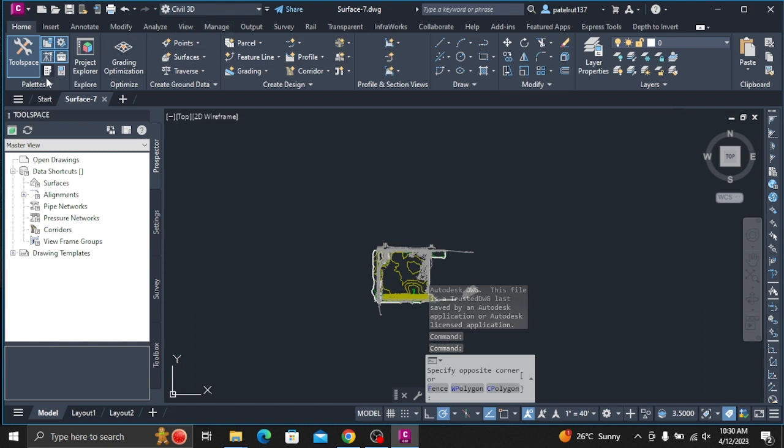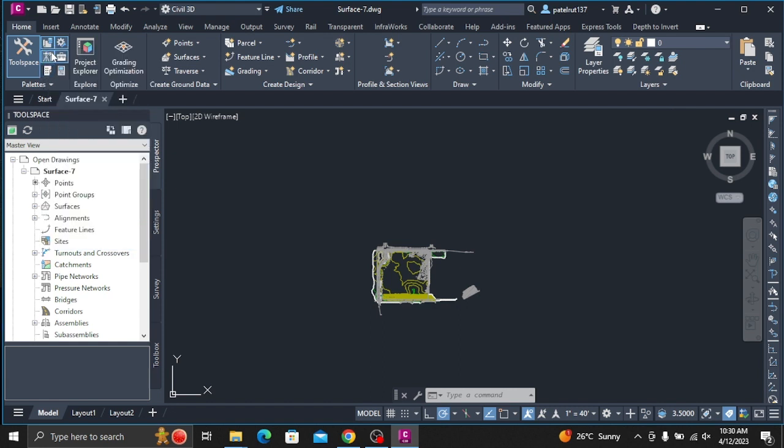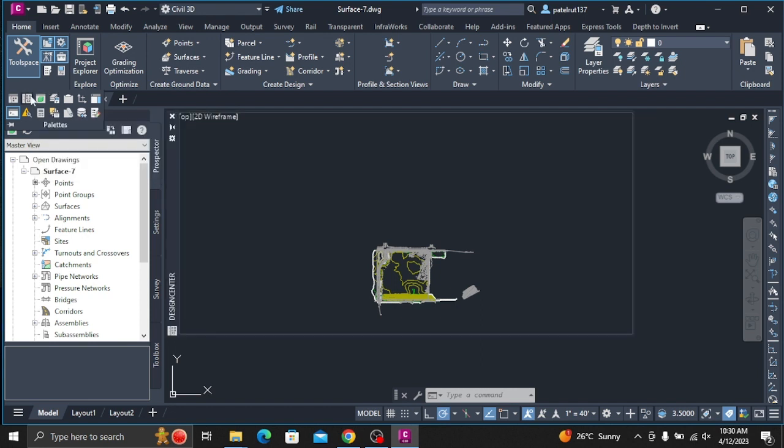In Design Center, navigate to the Data folder /symbols /blocks. Select the Blocks folder in the left pane. In the right pane, examine the blocks that are available. Note: before continuing with this exercise, either dock the Design Center palette or click to auto-hide it.